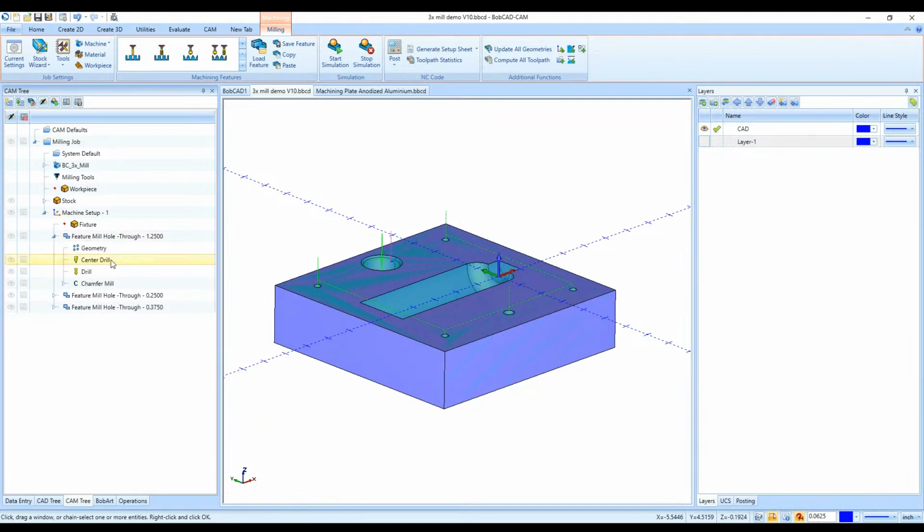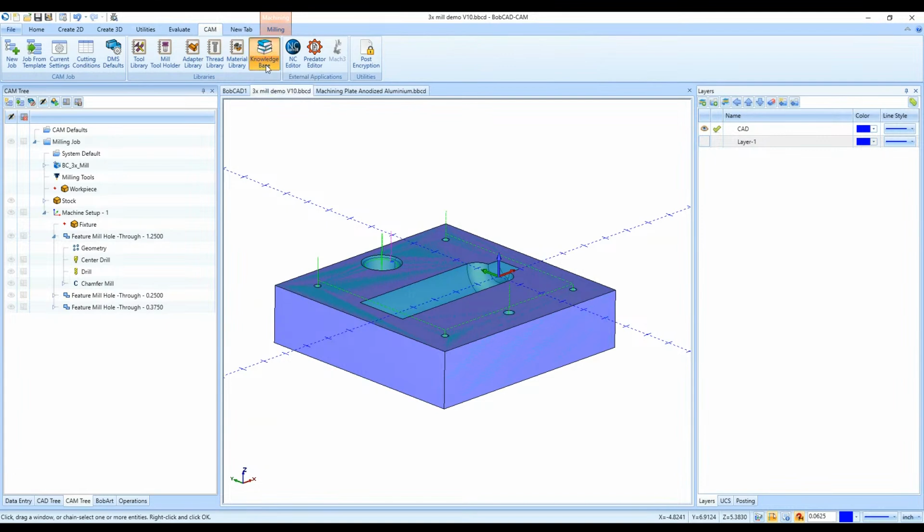And you've got all of the different settings that are saved under the knowledge base window here to set up all the different rules depending on the pecking for each hole size preferences, the chamfer drill or chamfer mill preferences for your specific holes that you're chamfering, and specific tapping preferences, settings there that you can save for next time.